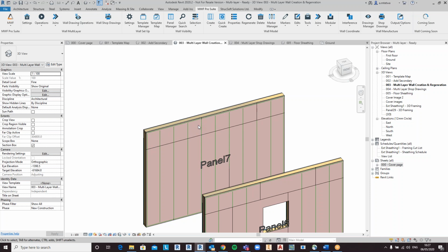However, these do still hold information that is transferable to the CNC machinery you see fit. For instance, if we were to have these lines set at 100 mil centers, although they will be displayed like this, the information that they carry will still hold that 100 mil centers information and can be read by CNC machinery.